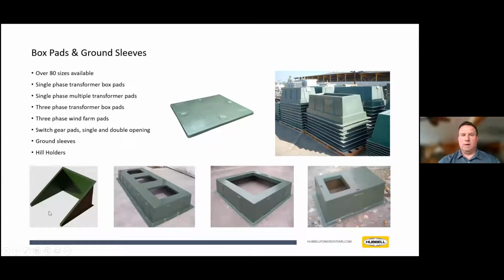And then the lower ones, we've got hill holders that can surround your box pads and support the area terrain from eroding onto the transformer or its box pad. The image just to its right is a triple gang box pad, a foundation that was used by a utility in Minnesota to gang up 3 single-phase transformers, effectively making it into somewhat of a poor man's 3-phase, if you will. Switchgear box pad in this picture just to that right, and then another single-phase transformer box pad that actually has little levels embedded inside of it.